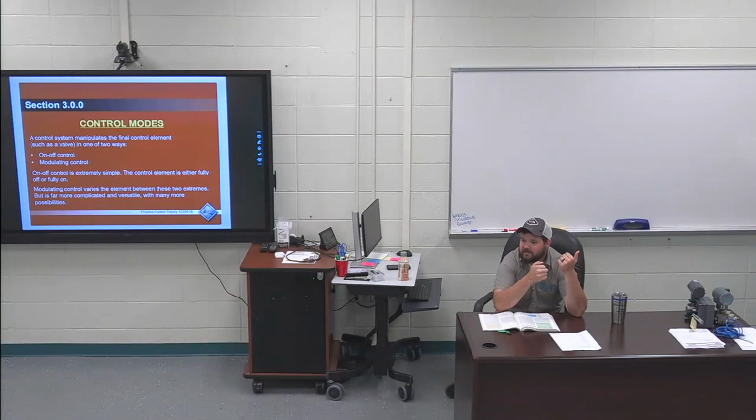Well, the reason they have hysteresis is we're sending that signal back to the controller. Let's make sure that this is an actual reading, give it a couple seconds, and then the controller can start making adjustments if that holds at 100%. Does that make sense? So hysteresis is pretty much a buffer. Whenever you hear the word hysteresis, just think of the word buffer.